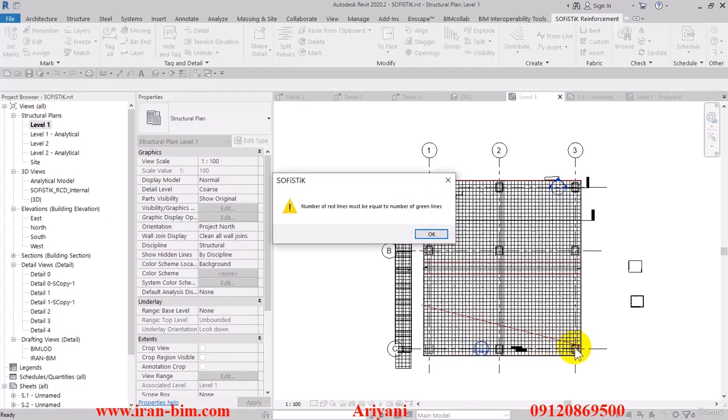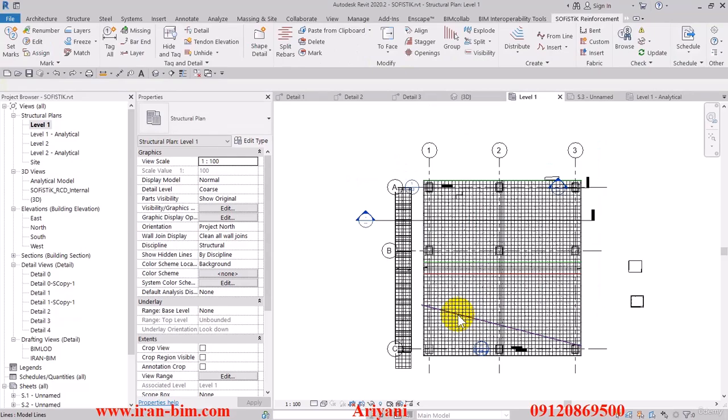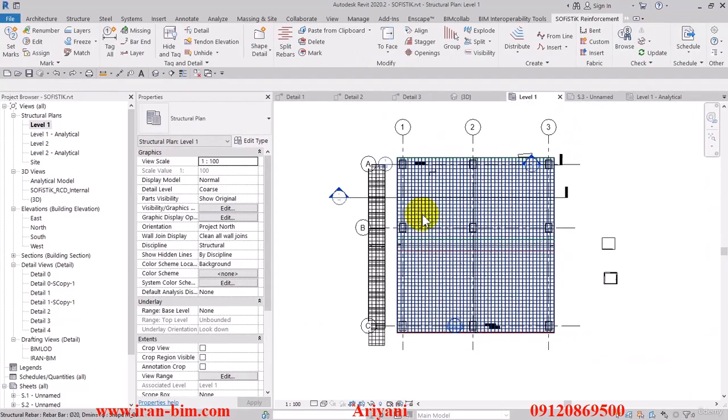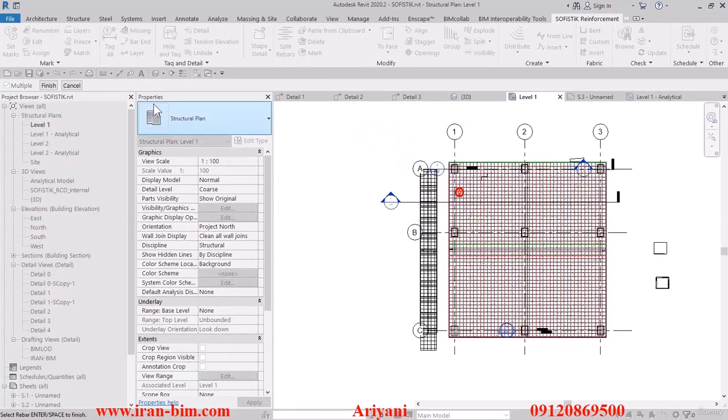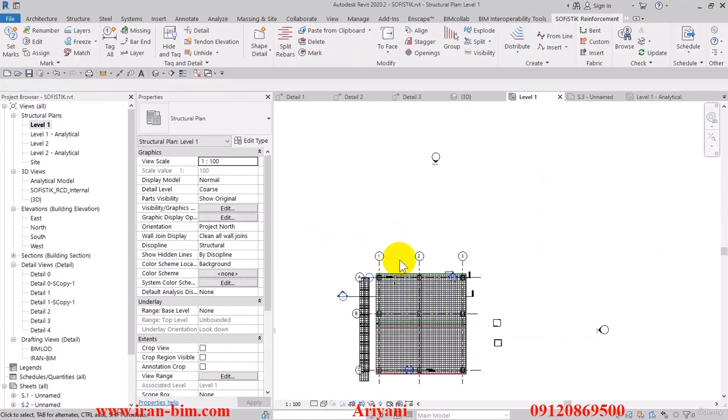The error is probably for the diagonal line that I've created. It's probably sticking out a bit. It's giving me errors, the same number as the lines that we have. So I'll just close this and then I'll select the line down here, Control Z, and Control Z again. After that, select the split rebars tool once again, select this and then finish, select the lines themselves and then finish again. And there we go. So how can these divide lines actually help us when we could have used the previous methods? I'll explain this in the next clip.